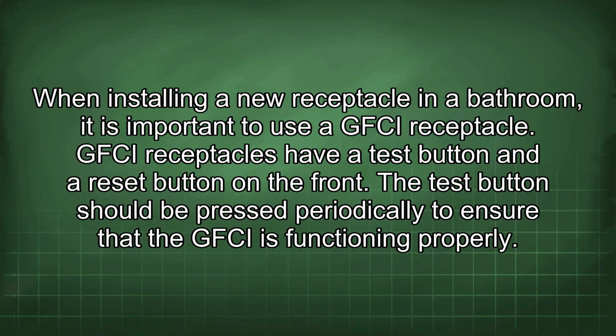When installing a new receptacle in a bathroom, it is important to use a GFCI receptacle. GFCI receptacles have a test button and a reset button on the front. The test button should be pressed periodically to ensure that the GFCI is functioning properly.